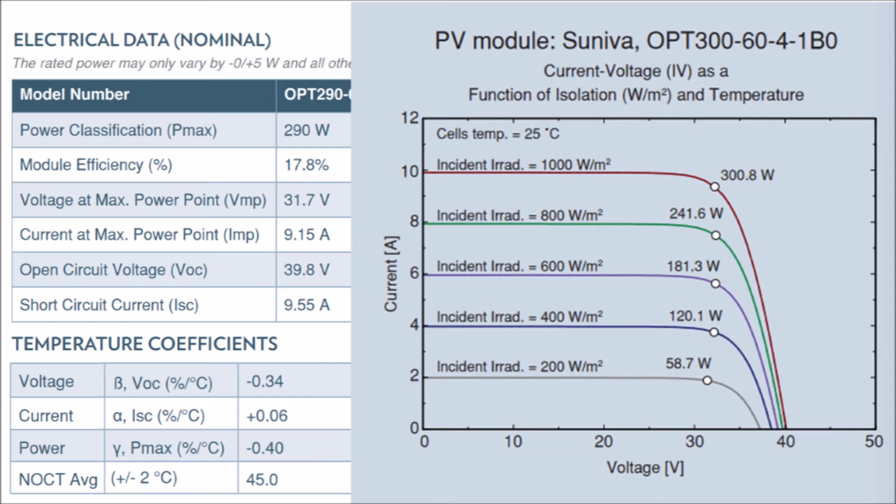The temperature coefficient of amperage is the opposite of the temperature coefficient of voltage. It has a positive sign, but the temperature coefficient of voltage has a negative sign. So whereas voltage will decrease with temperature, amperage will increase with temperature. That's worth pausing to memorize, that voltage decreases with high heat and amperage increases with high heat, having the opposite effect.